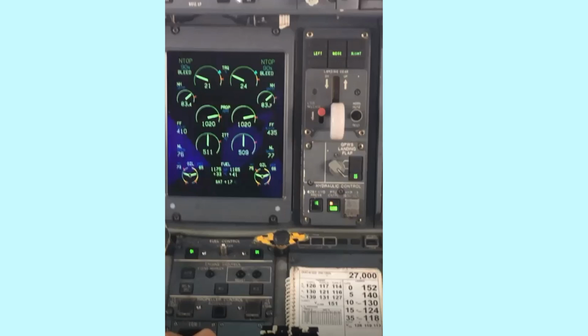You can recall that I just mentioned that our first explanation is what is that so-called magic torque value that we have to actually set in order to get a particular Vref for our landing. Vref meaning the landing speed. I'm hoping you are able to see the cursor. The torque value appears on these torque gauges on the engine display.